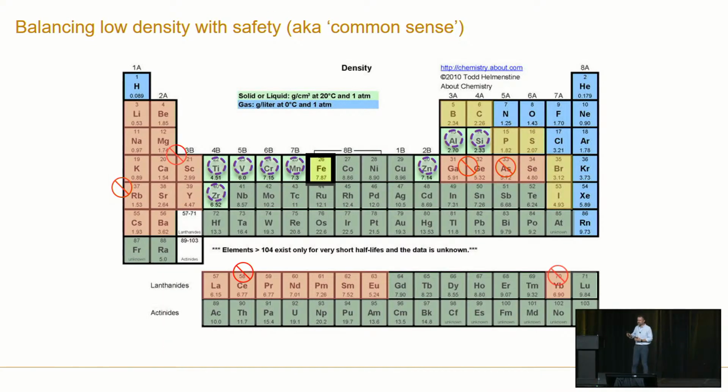So what did we do then? Before we went into all the details and the fundamentals, we thought this is really exciting. What can we try that's really cool now that we've discovered something that we think is perhaps universal across this alloy system? So if you remember earlier, I showed you a plot that had high entropy alloys being very high strength, good mechanical properties, but also very high density. So their specific properties weren't that good. So I thought, wouldn't it be great if we could make really light ones if they're going to be really corrosion resistant? That's much better than, say, using stainless steels or using other materials that are usually quite heavy if corrosion resistance is the key.